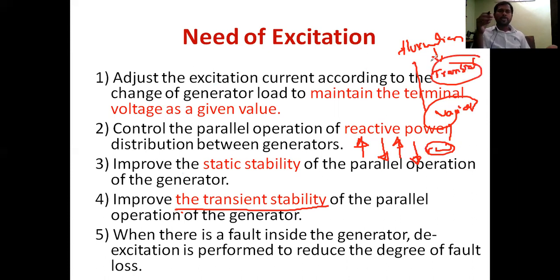In your home also, if you turn on a load suddenly, for example a water heater, a geyser, a refrigerator, whatever it will be, a huge load, another load will get disturbed. Somewhat disturbance will take place. Such a disturbance is called a transient. That transient should not affect the alternator. Sudden falling or sudden rising of the load causes some voltage variation. Those variations or transients can be decreased with this excitation.